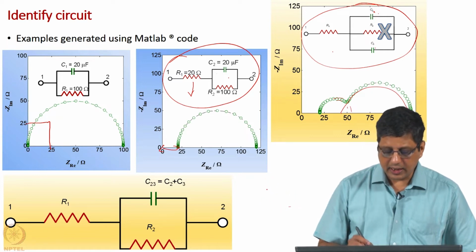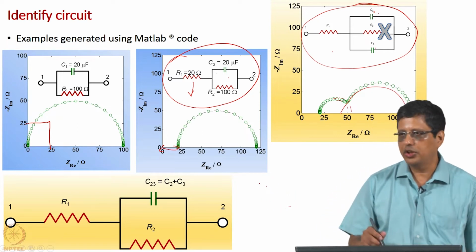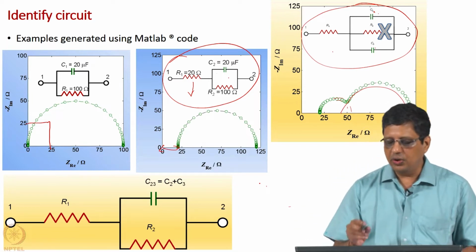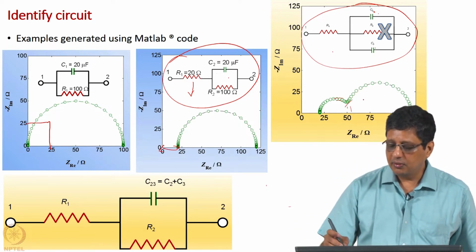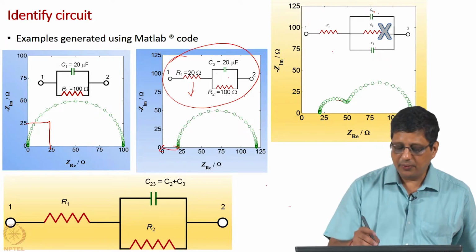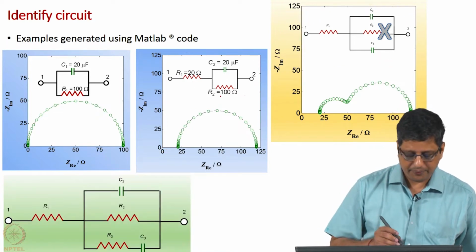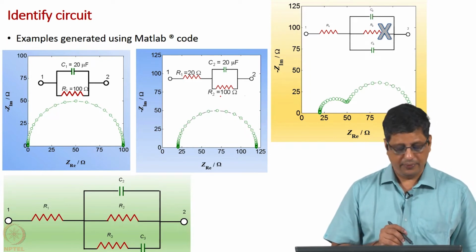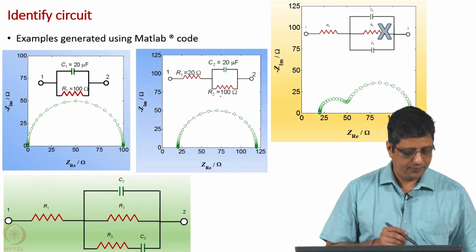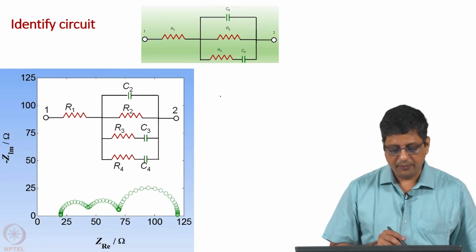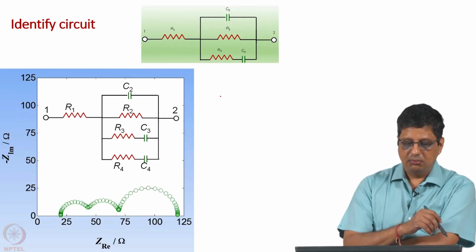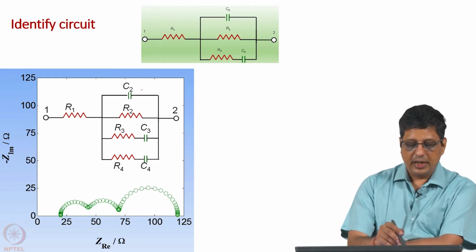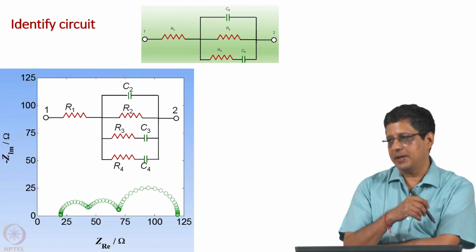Of course, I can add in the ladder format, I am not showing you here, but all of this will give you data in this format. So, all of this will be able to model this equally well. So, I can choose a Maxwell representation and say this works well, this will be able to fit the data. If I see 3 loops, I would say I can use C2 R2 and then 2 more RC pairs.